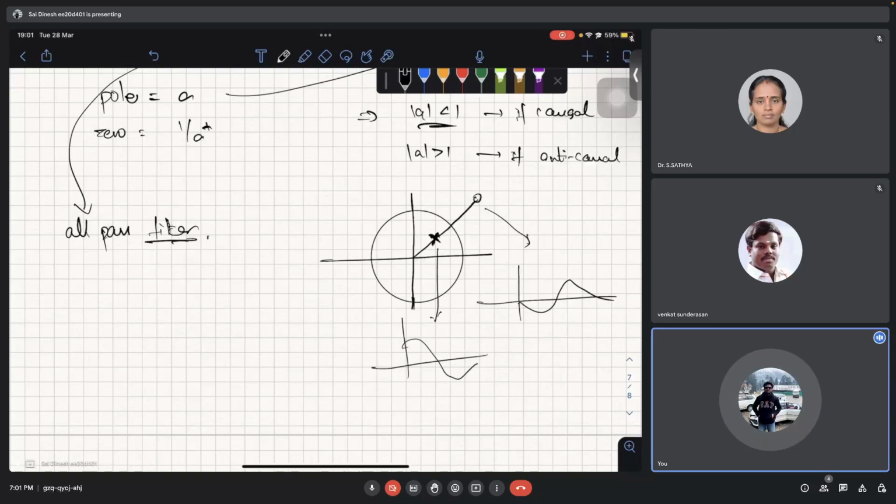But then we also have a difference in the amplitude, is it? So now how does it change? No, right? So this is what you need to find out. This is an all pass filter, and all pass filters do not affect the magnitude response, but they do affect the phase response. So that is why they are used for phase compensation, right?